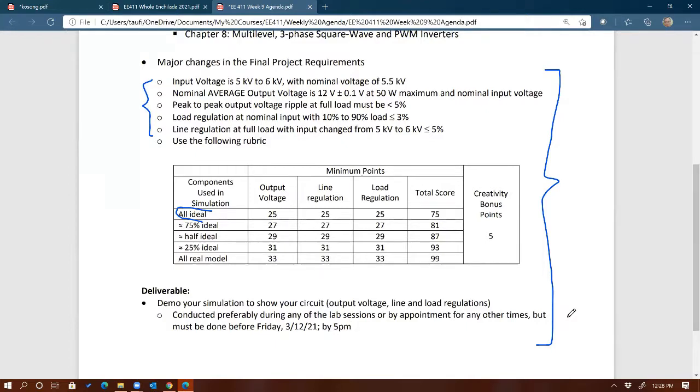Yeah, so it is tough. It is tough to get a very efficient system when the difference between the levels of voltages between input and output is very large, such as this one, right? Yeah, I never realized that even a sub-ohm on resistance of a device actually starts to matter when you put like 10 of them in series. Absolutely, yes, exactly.